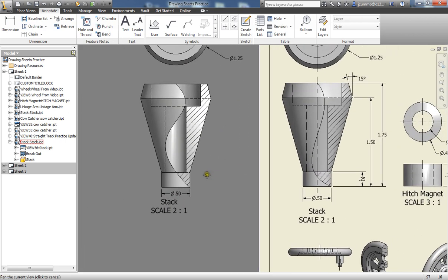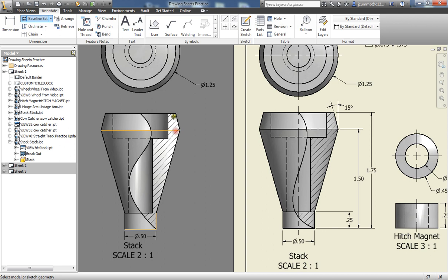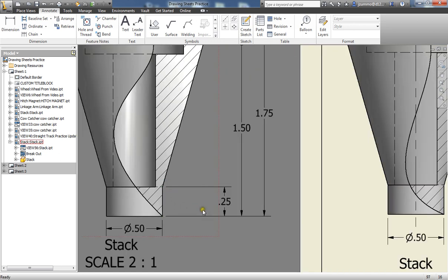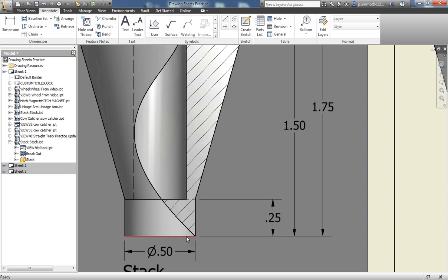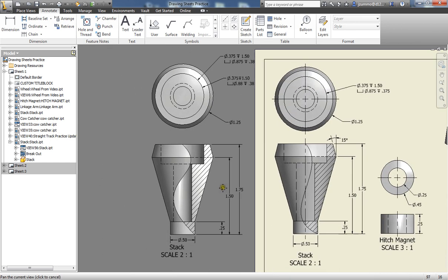I'm just going to go ahead and redo that one more time because I'm particular about my dimensioning. I'm going to select those lines again, left click, continue, right click to place. I can see now that that 0.25 is properly spaced off the part the way I wanted it. So it's probably better just to select the bottom line, this side line here, this line here, and that one at the top to create those lines.